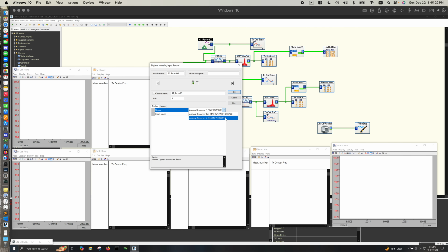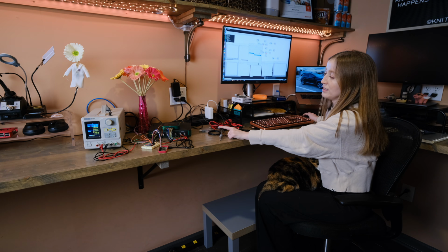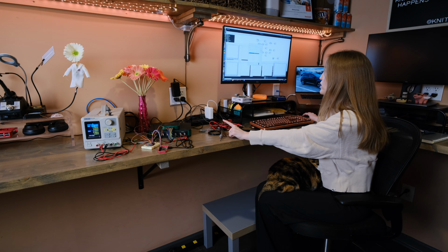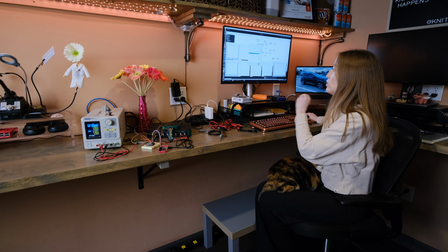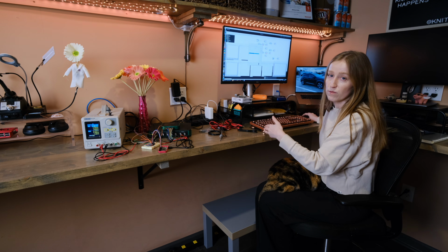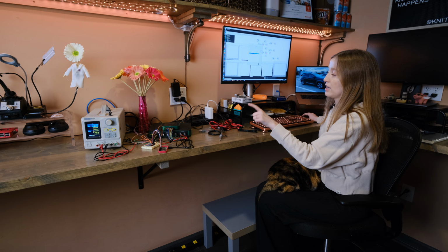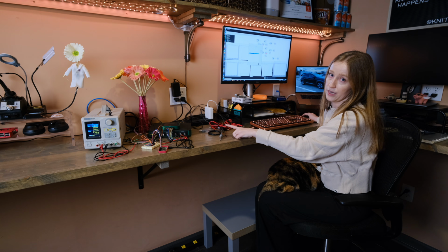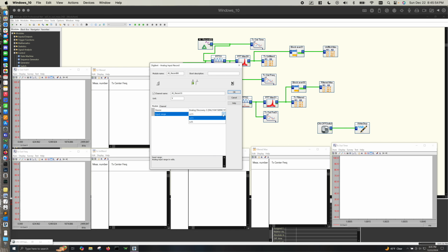The only reason I'm not using the 3450 right now is because I'm using the logic analyzer function, which, because this particular driver, the Digilent driver, is in beta form, the only thing it can do is the scope function, so just read an analog waveform in. So it's automatically selecting channel 1 of the scope on the Analog Discovery 3. I can change the input range, so the Analog Discovery 3 can do plus or minus 2.5 or 25 volts. I set the unit, I'm measuring voltage.